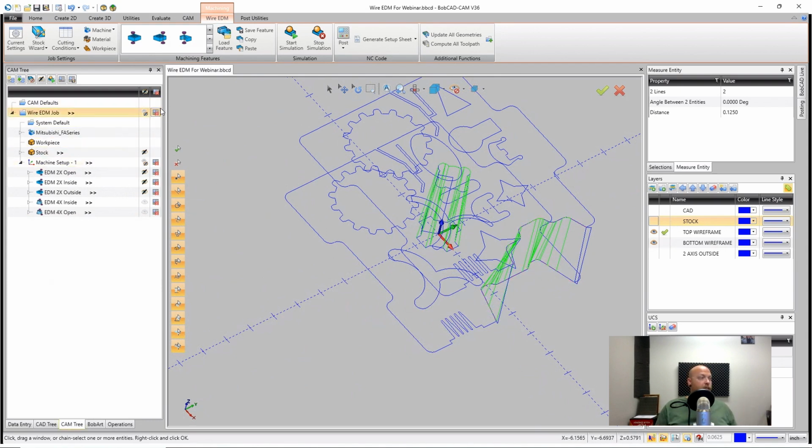You can copy and paste from one window to another window. So if I'm working on a job where I'm doing something that I've done before, but I don't do it often, I can open up the part that I've done before, copy that toolpath and steal that one, bring it over to the other job, paste it down and run it again. And it speeds up the entire process.